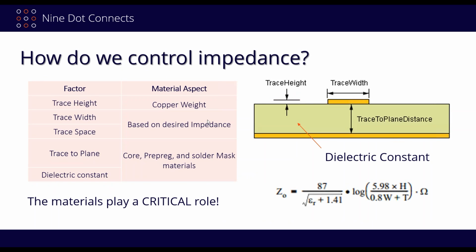Well, interestingly enough, when we're dealing with impedance, obviously routing has a huge thing to do with it. But before we even get to the routing, we have to have the infrastructure in place to control the impedance. And when we look at the impedance equation, one of the things you don't see in this equation is length. Okay, length does have an issue with antennas, and we talked about that in other webinars. However, when you look at the impedance calculation, it has to do with several other things that are very, very specific to your board. What do we mean by that?